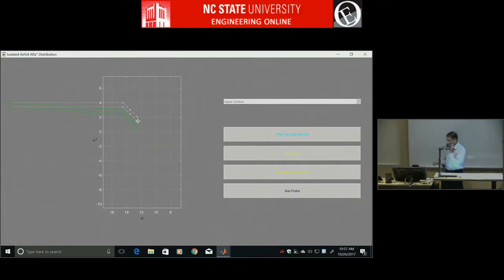We'll kind of write all this down as well. But when you want to do cursor edit, so normally if you click on the plot, it'll zoom, right? So you can draw a rectangle and then double click, it'll come back to the original zoom. You can single click and it'll keep zooming in. And if you right click, you can zoom out, or double click and it'll go back.